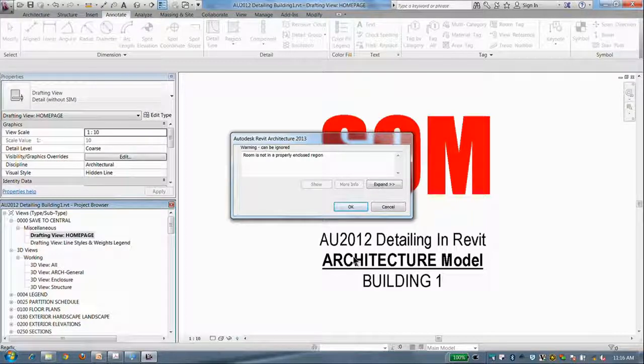There is a feature in Revit where if you detail something once, whether it's with a drafting view or with other modeled stuff, you can actually call that out over and over again. That's called reference other view. Every time you go to create a section, a callout, or a plan detail or an elevation, I forget, there's an option on the option bar, reference other view, and you can pick that detail that you've already created and just reference it many times throughout your project. Is that your question? No, I went off the topic there.